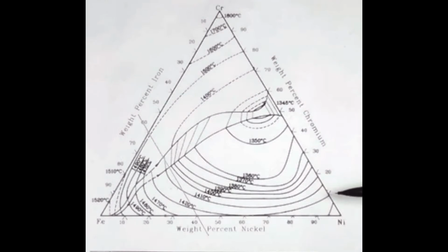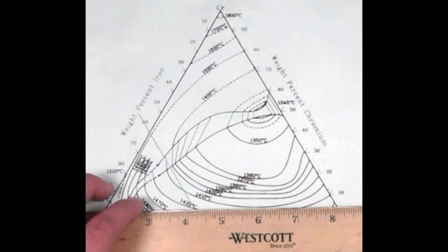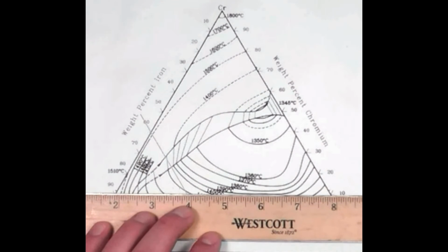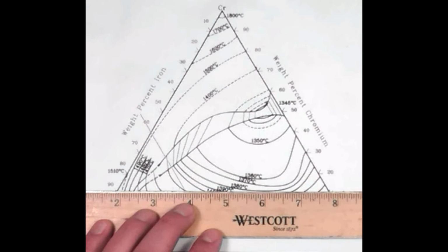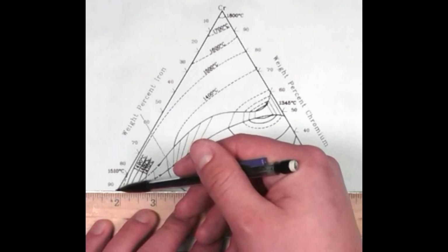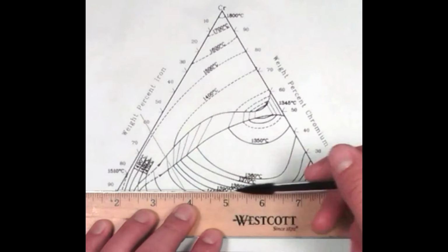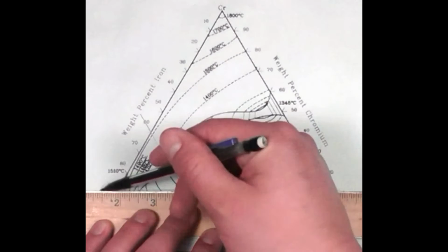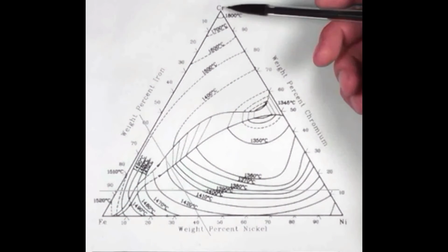If we were at 11.5% chromium, and we think of this as a binary containing only chromium and iron, our composition of iron would be 88.5%. By constructing a line between these 2 points, we will obtain our parallel line opposite that of chromium.